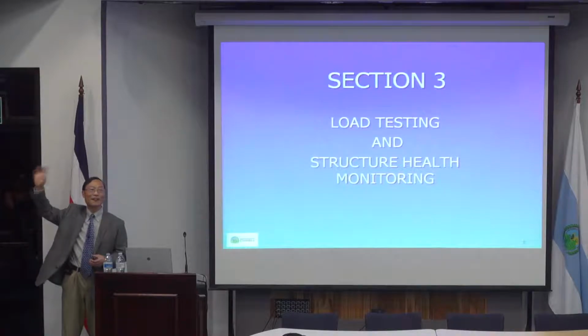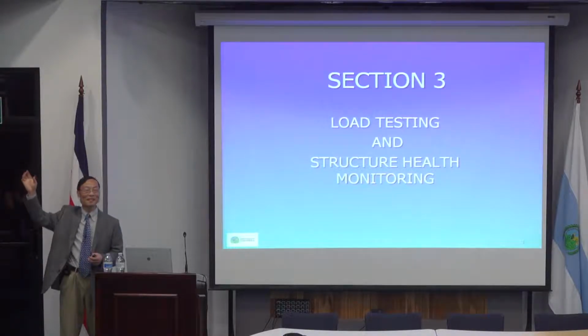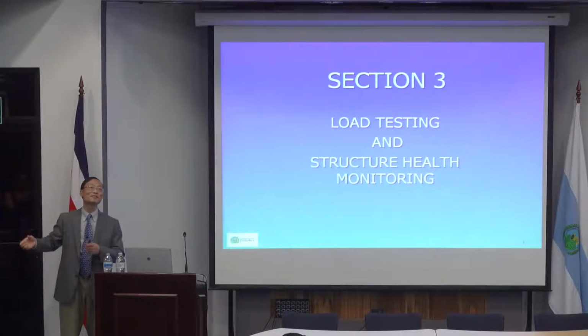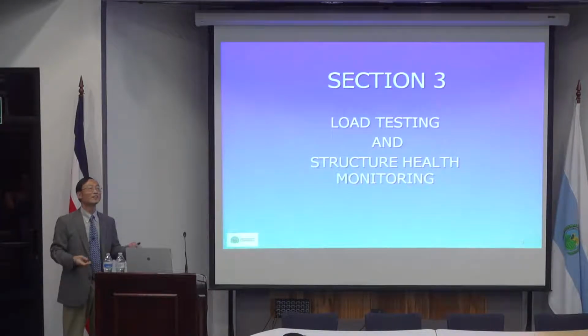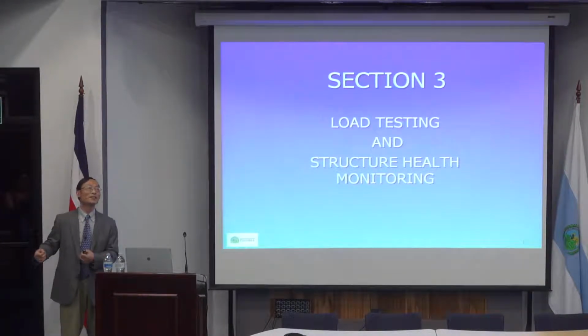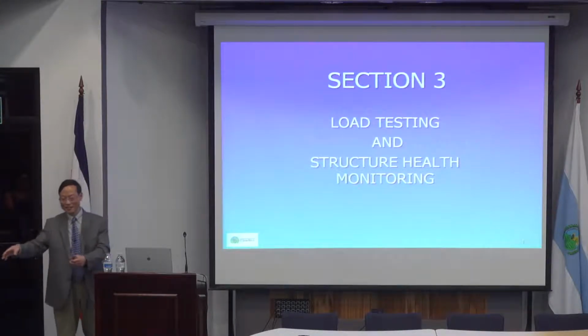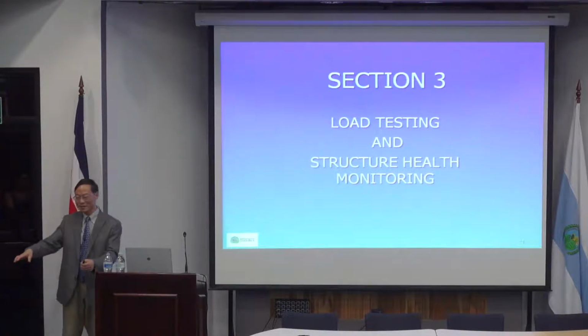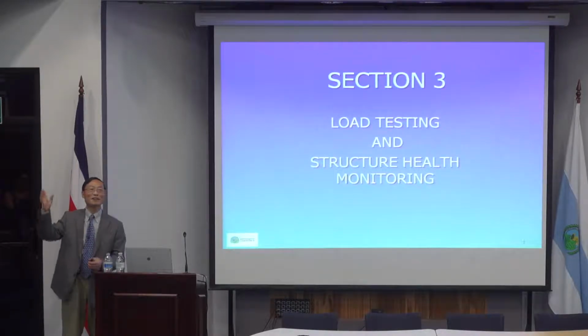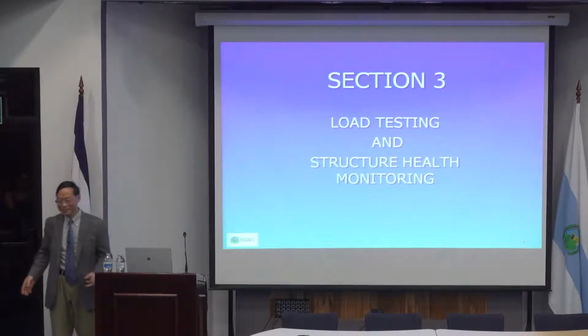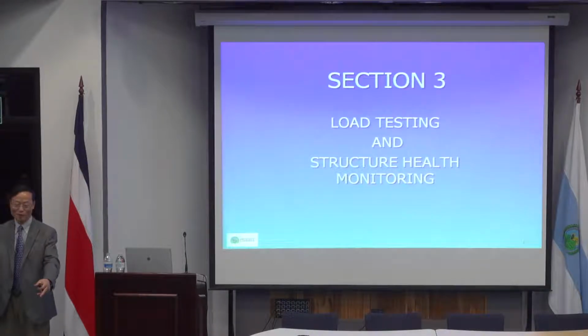One is how live load is distributed. Once you do a test, that will be relatively easy. You just bring a regular truck. It can be any type of truck. Of course, if it's very similar to the design truck, that will be good. But if not, you just designate the spacing, and you know the total weight and the weight of each axle. You just ask the truck to stop and park there.